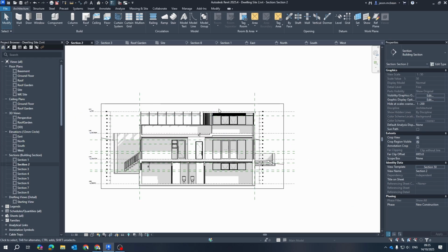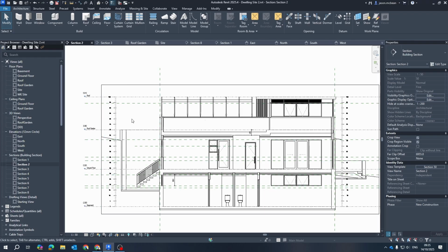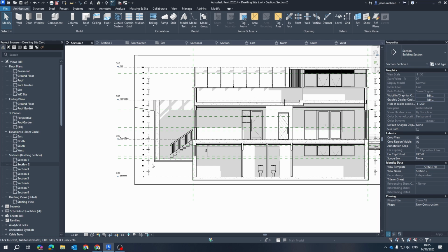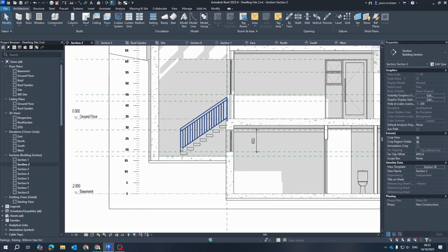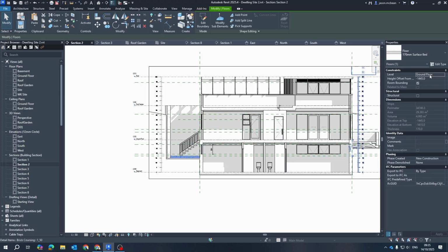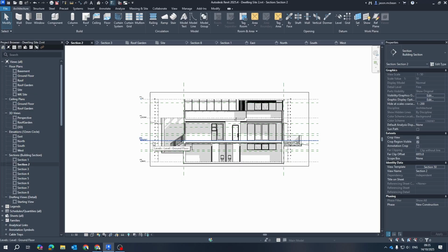Okay, so that's this model in a nutshell. I've used a bunch of levels, and you can see with levels, don't add a lot of unnecessary levels. So you see I haven't added a level for this basement level. I understand that this floor will be relative to something else, and you can keep seeing a ground floor minus ground floor. So don't add unnecessary levels because it gets a lot more difficult to manage. Just understand that each level you can customize what you're seeing.